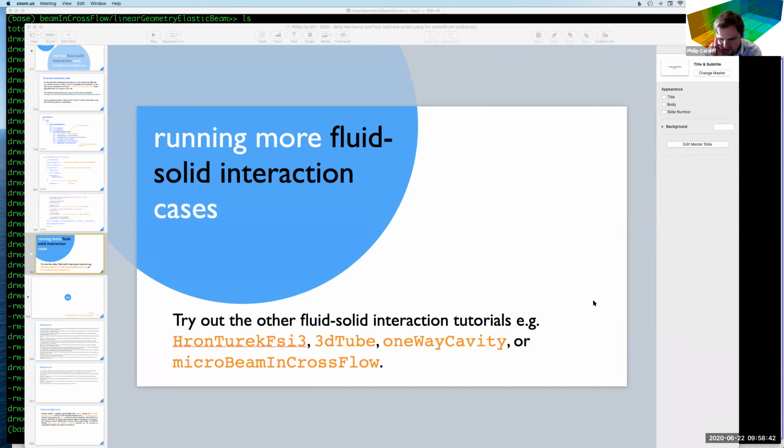Thanks for the presentation. Recommendations for transient FSI with large deformations? Solid dynamics early is a major effect. You see a jump in deformation of the solid patch after zooming, and the simulation stops. I'm not sure of the reason. Okay, so a couple of questions. Recommendations for transient FSI: it depends on the type of case you have. Typically for the large strain solids, the nonlinear updated Lagrangian, or UNS nonlinear updated Lagrangian, typically converge the best. You might need some relaxation factors with the field, maybe down to 0.5 with the D field itself, if you're struggling with the solid convergence.